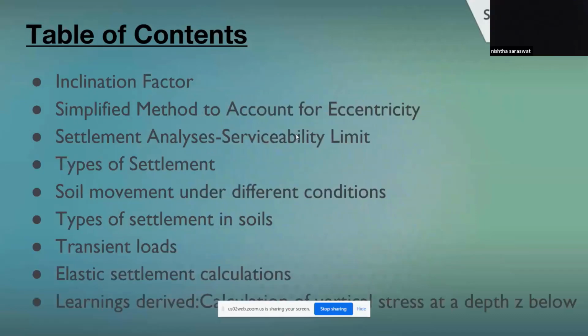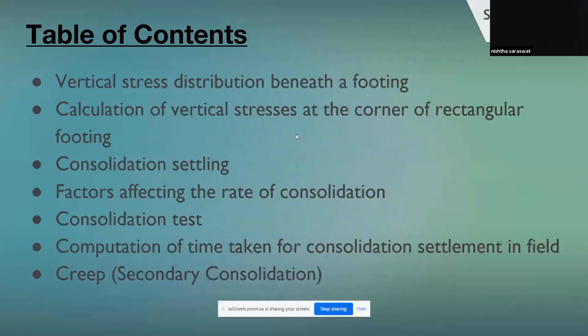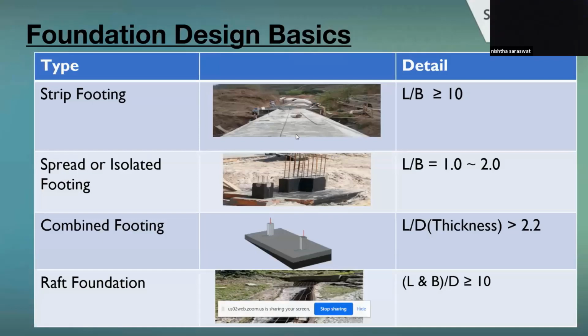So to begin with, for foundation, I will be addressing foundation as substructure, and the structural elements would be classified as superstructure. For any kind of superstructure, be it a building, road, or highway, it has to be founded on soil so as to transmit the loads to the soil. In an easy way, we can classify foundations as the substructure components which transmit the superstructural loads to the earth or ground in a way that it does not undergo deformation that would cause settlements.